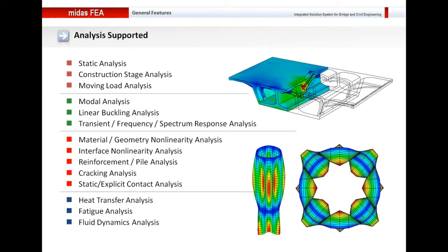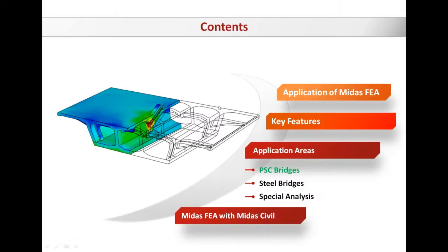And these two things combined, the geometric modeling features combined with the mesh generation and the FEM solver, can be used to perform many types of analysis. So here you can see you can perform static analysis, construction stage analysis, moving load analysis, and other special analysis. I'm going to talk about these types of analysis once we go through specific bridge types in Midas FEA. So now let us talk about pre-stressed concrete bridges specifically in Midas FEA.